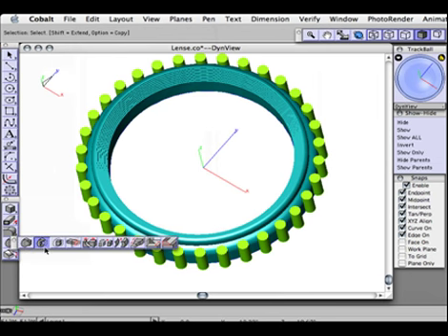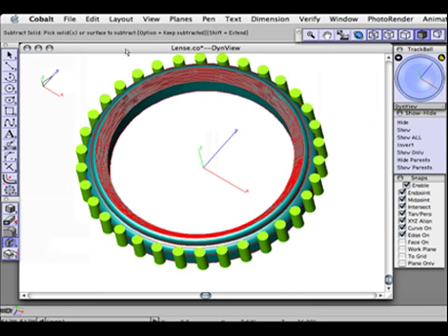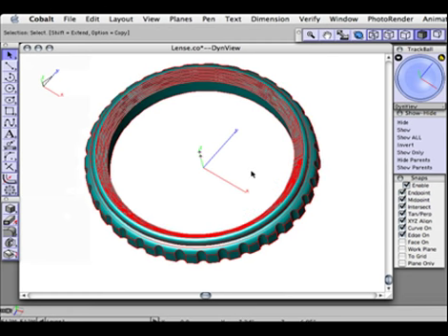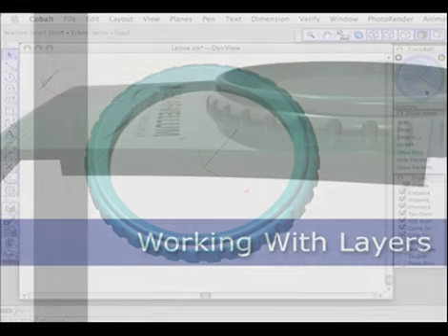Now we'll choose the Subtract Solid tool, and notice it says Pick Solid to Subtract From. So I want to remove parts from this lathe. It says Pick Solid or Surface to Subtract. So I want to subtract those cylinders. Remember, just by clicking one of them, because I extruded them all together, it's going to count as one selection set. So it subtracts all of those cylinders from our ring. Click on Show Only, so it just shows our part, and we have a nice looking solid part.